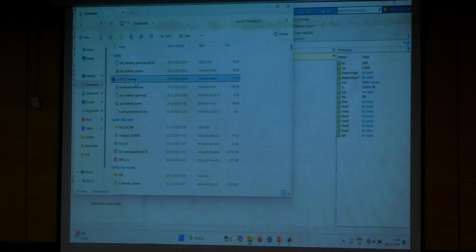Can you comment something on the virtual voltage vector? A virtual voltage vector in SVM is also there. Those are the methods. As I remember, whenever redundancy is not there, we inject some vectors, or we assume some vectors are injected, and based on that we do the calculations.